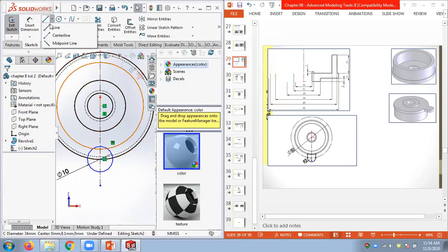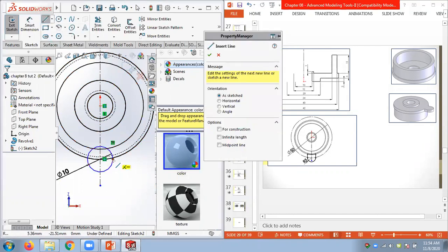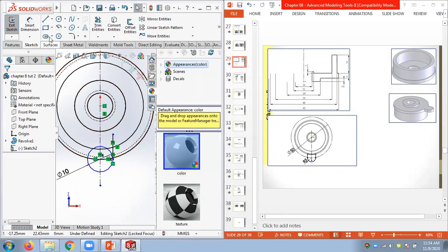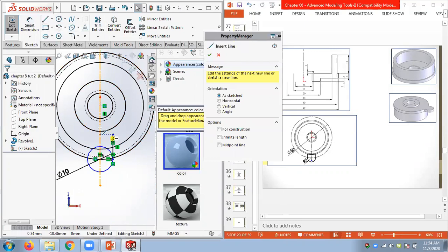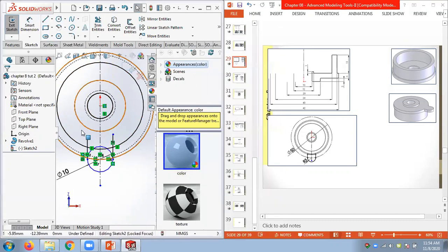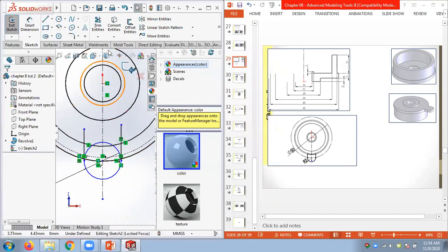Then we can just use this quadrant here and extend these lines here. If you want, you can mirror, or just offset this one also. So I'm getting quadrant snaps here and getting up to here. Then we can trim.